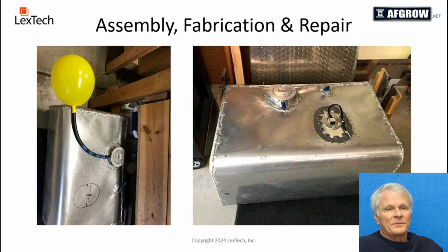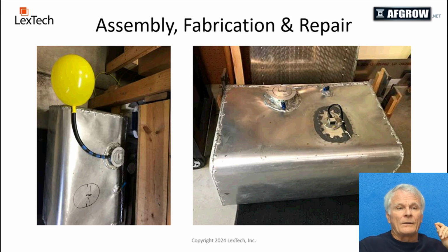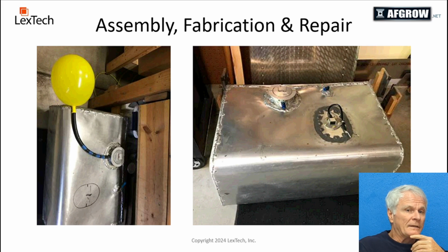Now the fuel tank, I was really concerned about the fuel tank. The reason why the airplane was taken apart was because the original fuel tank was fiberglass, and it leaks, so it all had to come apart. And this is the new aluminum tank that Skeeter had built, and I wanted to make sure that it had no leaks. And then I also wanted to install a fuel sender, so I cut it open and added the fuel sender to the top of the tank.